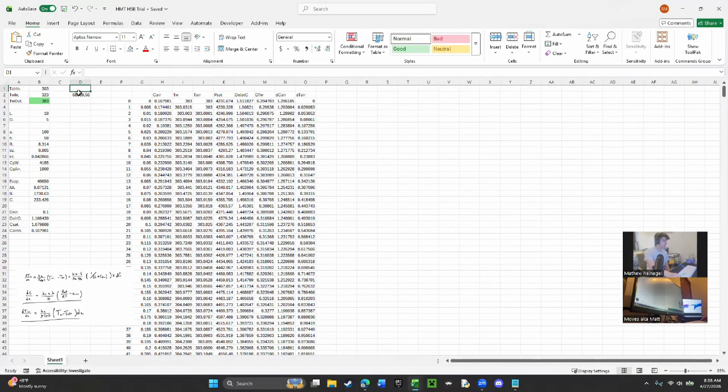So at this point, we have the amount that we have grown, and we want to look for some desired temperature out. For the desired temperature out, what we want is the temperature of the water coming in. So we want to say that our desired temperature is 323 in this case, right? So let's say this equals, we're going to do a sum squared really quick: 323 minus this value, to the power of 2.